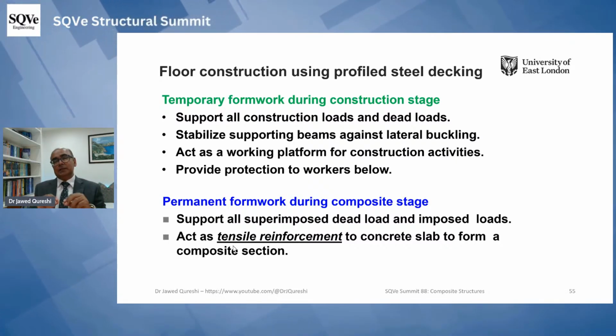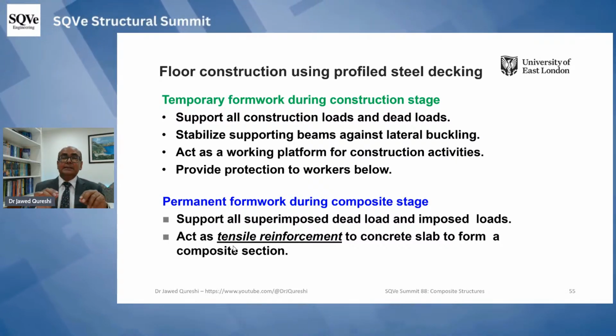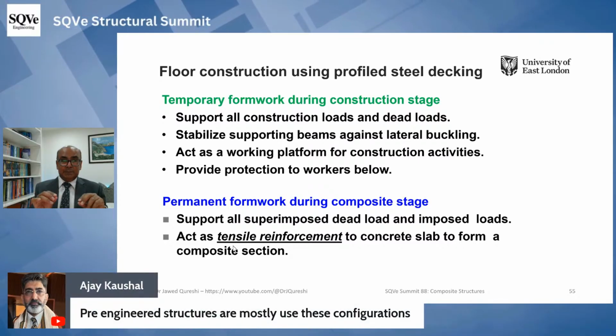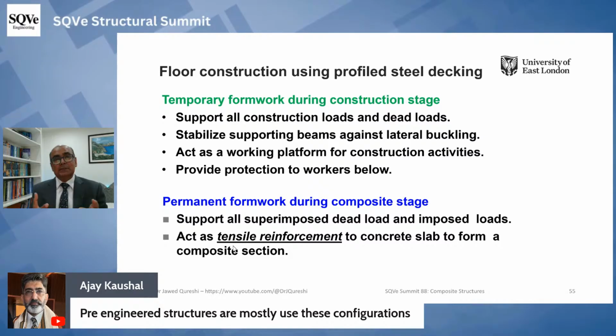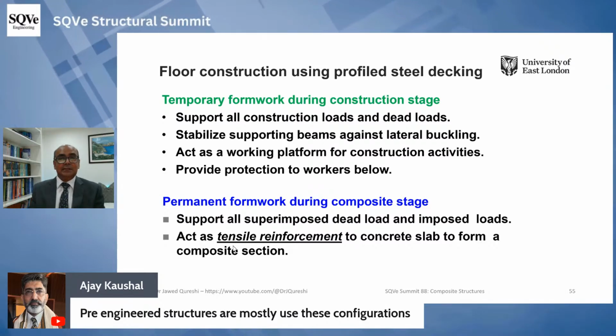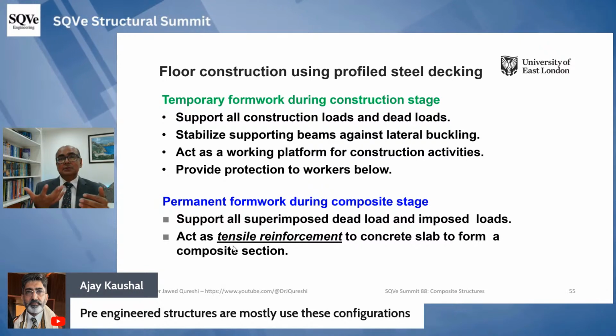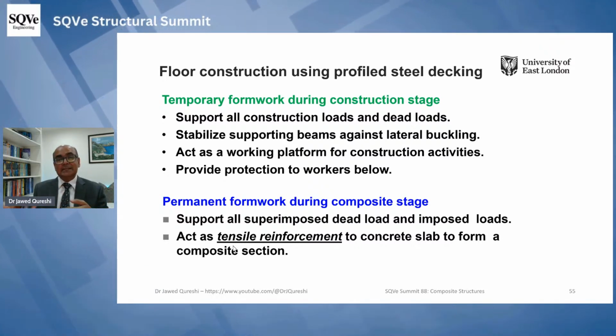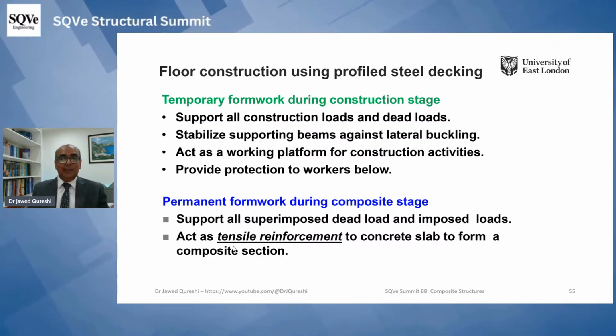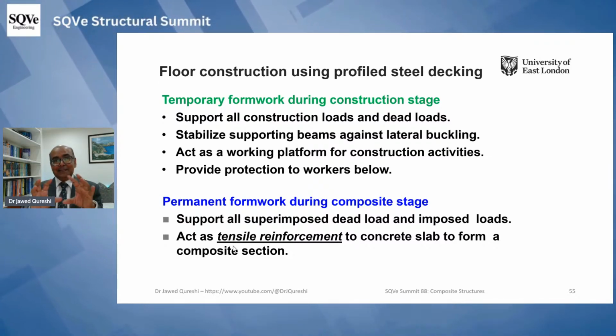The key thing to take away here is that it acts as tensile reinforcement to concrete slab, and in that way, it forms a composite structure. So there are two purposes. It is formwork where it is being constructed. So once concrete is hardened, it acts as tension reinforcement. If we didn't have a steel deck, then imagine what will happen. The slab is going to fail miserably, and it gives a shape to concrete as well, because concrete can be molded into anything.